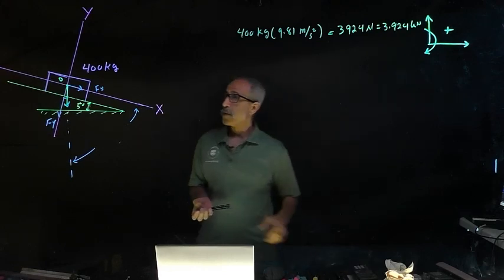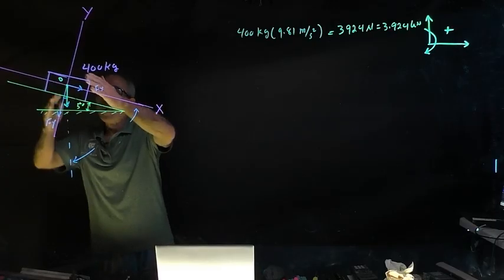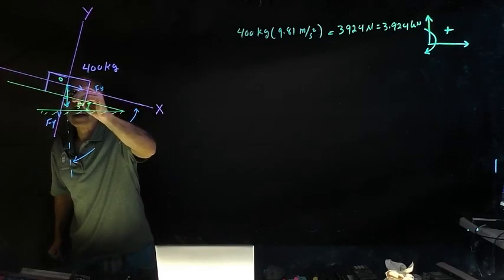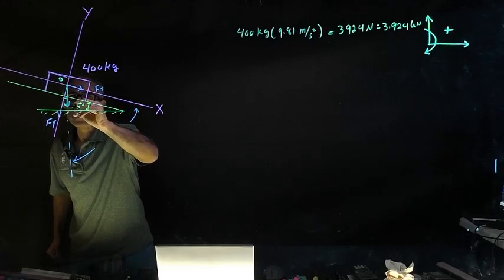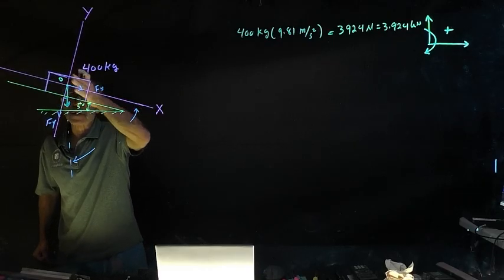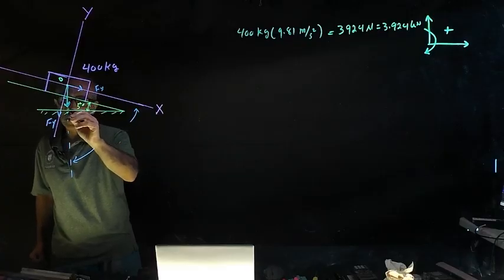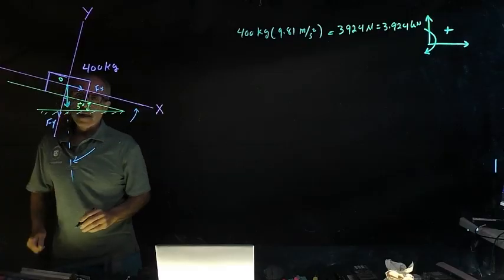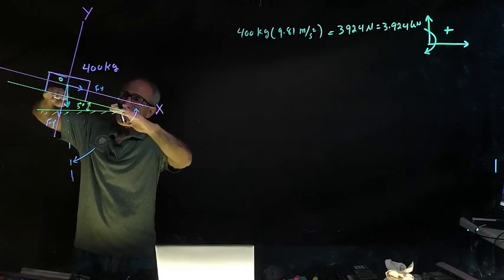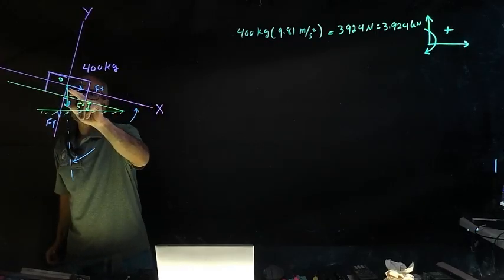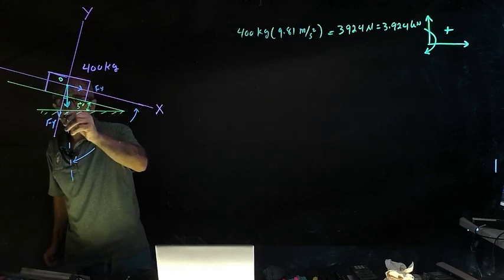Okay, so now we know the weight of the block is right here. It's vertical, gravity is vertical. So that's the weight of the block coming down vertical right here. But because the ground is on a slope of 5%, our Fx is going to be along this line right here, and our Fy is going to be down at the y.